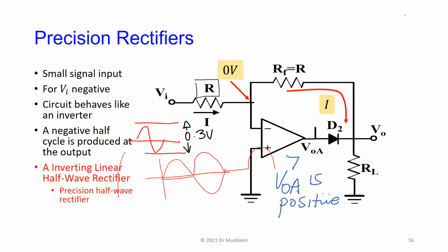You can increase the value. Typically, the op amps will tolerate maybe a value up to about a megohm, right? And that's about the sort of limit. What I have is 1 megohm, right? Which is about the limit of the size of these resistors that you can use with typical commercial amplifiers that you would get.